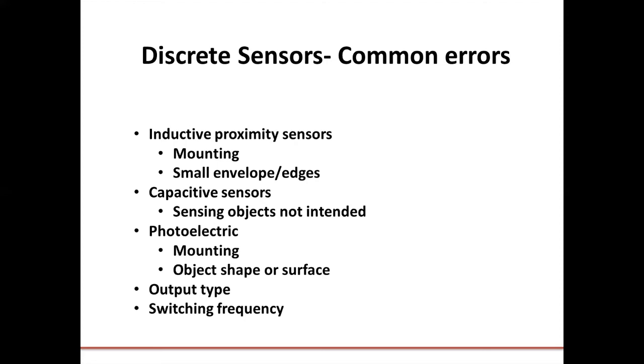For most industrial proximity sensors, the cylindrical type, you need to be aware whether it's shielded or unshielded, because oftentimes if you mount it too close to an object, well, actually, I'm sorry, mounting it very close is a good thing, but if an object is not directed or placed so that the sensor can detect the object at its furthest point along a certain boundary, it won't detect the object and therefore it'll miss a count.